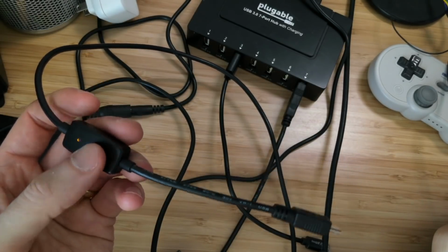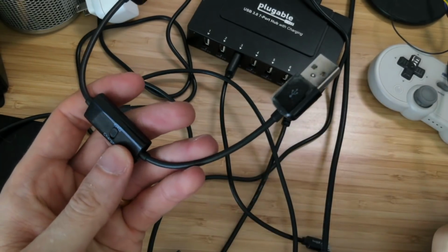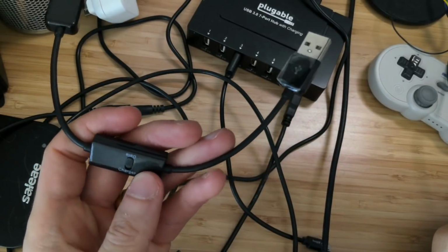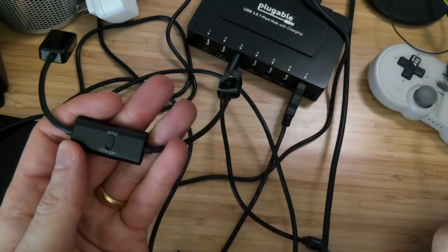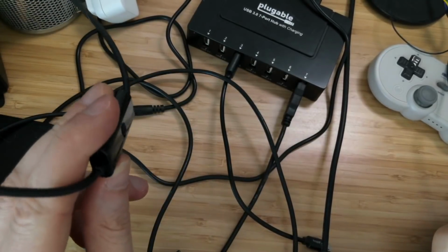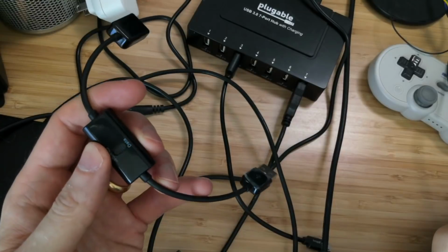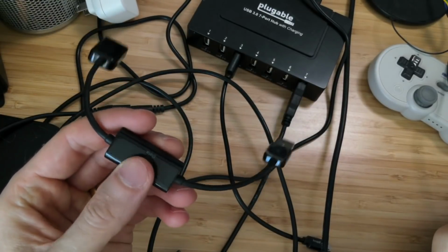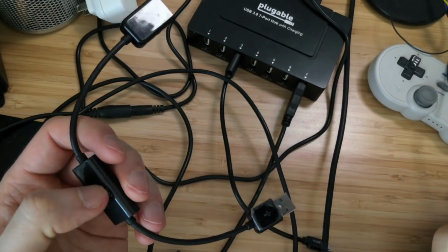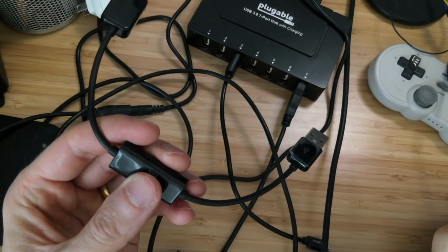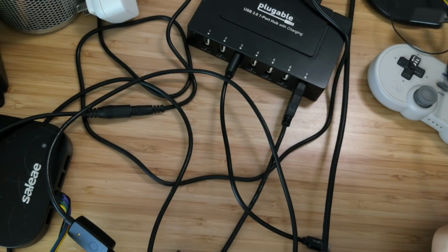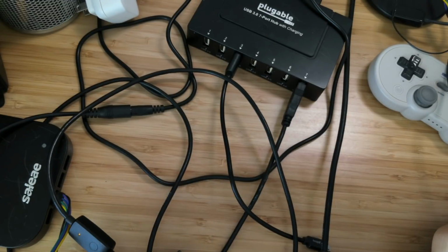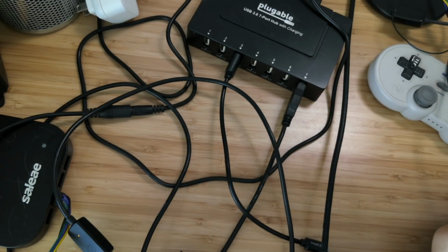And then I showed this cable to Limor, and she actually stocks on Adafruit a similar cable. It's just like a pigtail, nice and short, but it's got a switch that says charger and data. So you can just switch it between, turning the data lines off and on. It's super handy if you ever are doing USB debugging. What I was finding before I got this set up is that as you're working on your USB code, you can get it into a hung state. I like to listen to music while I'm programming, and I'd find the music would stutter and stop as I'm stalling the USB bus because I'm not doing the right thing. So these cables are a lifesaver, so that you can quickly disconnect the misbehaving device, your own device, from the USB bus.